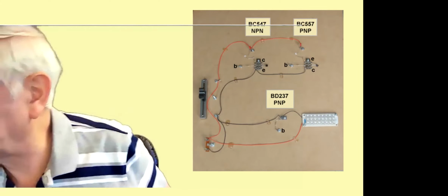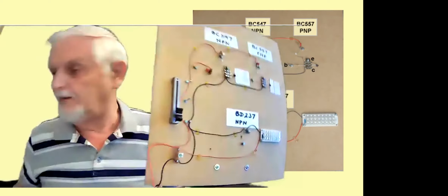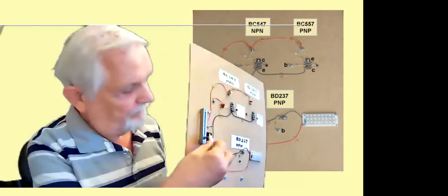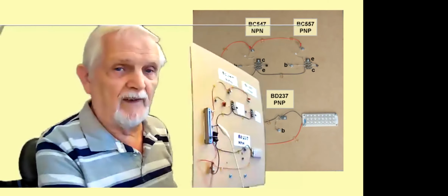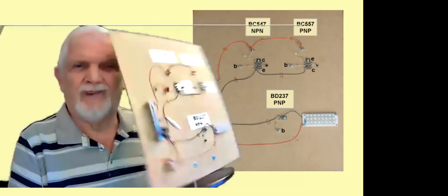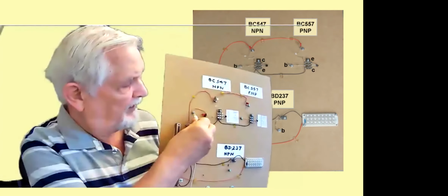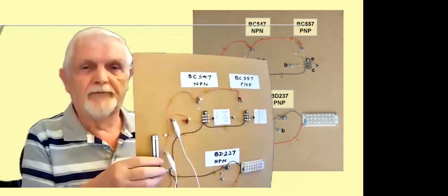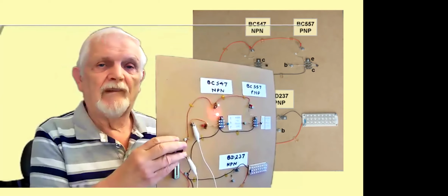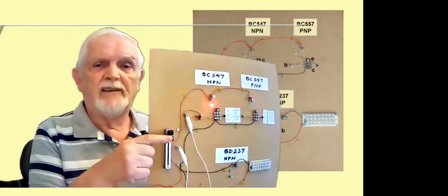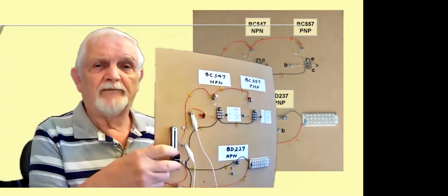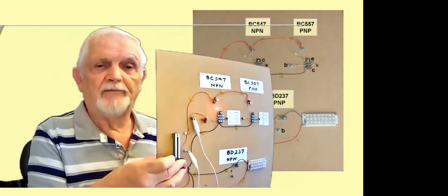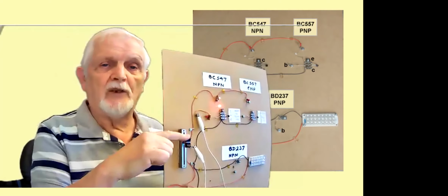Right, let's see. As it stands, nothing. But what I'm going to do is connect there, like I said, to the base. When it goes high, can you see the LEDs illuminating? It is an NPN type, so going high should switch it on. It does. Going to 0 should switch it off. It does.